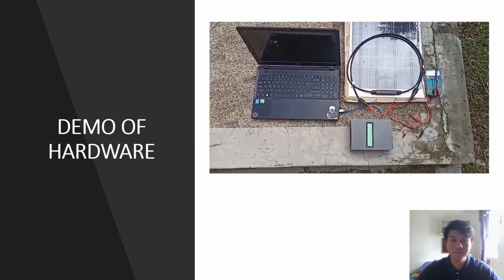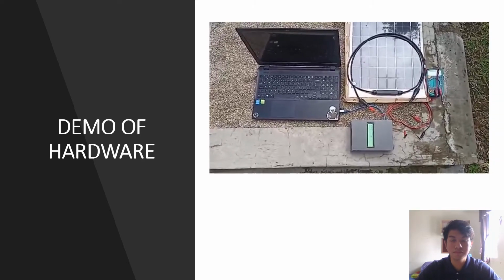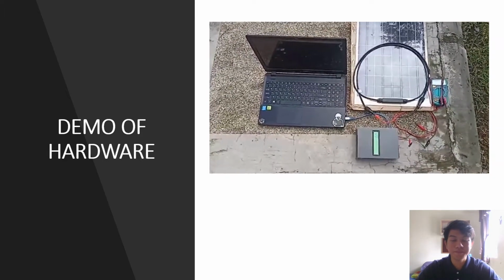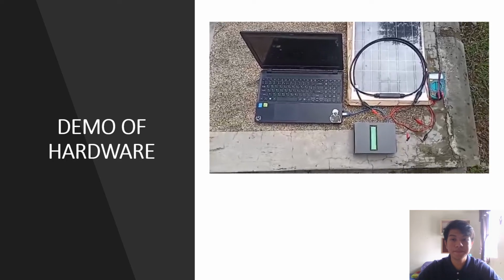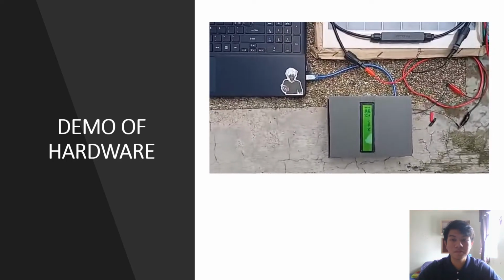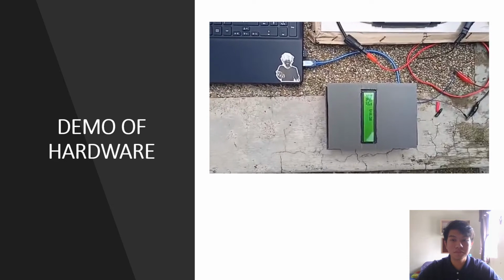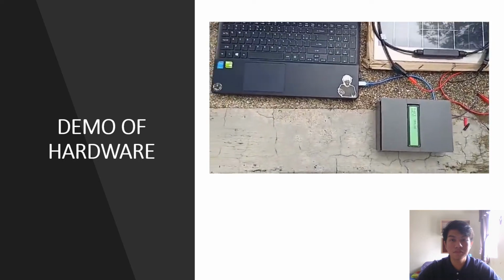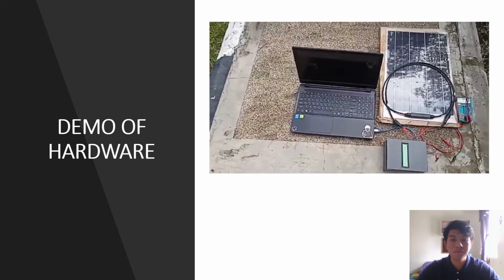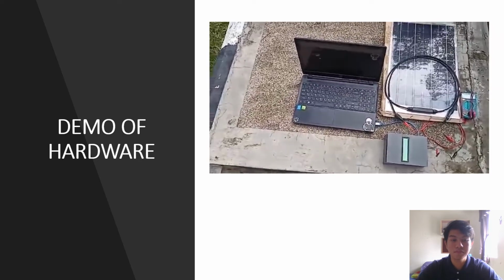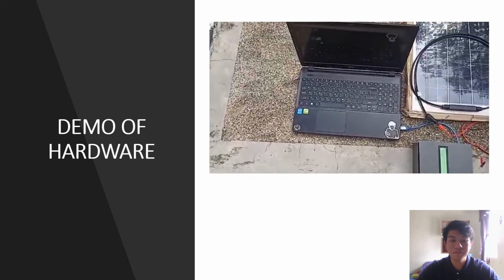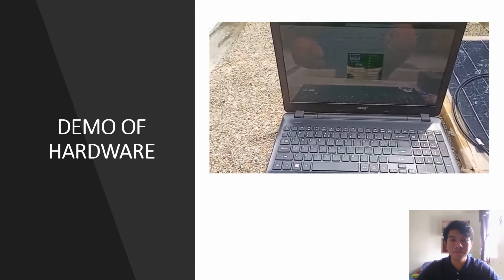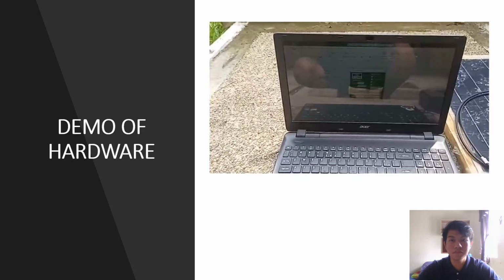For the circuit hardware, a safety cover has been made to maximize safety during the test. Next, when we connect the PV to the circuit, the parameters of the PV are measured, such as voltage, current, and temperature. Then we connected our circuit hardware to our laptop to read and record the data measured by the circuit hardware. For this part, we use PLX-DAQ software to record the parameters, as it is a convenient way to record them, since it links the data to Excel.